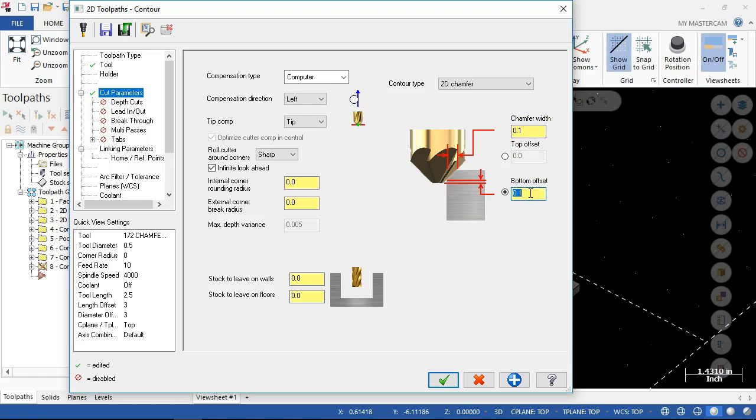All right, so if I was going to use the 1/4 inch, 20, 25, 30 thousandths would be right there at the diameter. If we tell it to go 0.125 deep, it's going 0.125 over. All right, and depending on how much it programs for the offset, we're using every bit of that 1/4 inch tool. And again, there's not a lot of surface feet per minute going on at the tip, so we have more cutting action going at the larger portion of the diameter, and not so much at the tip. So we'll see what we get.